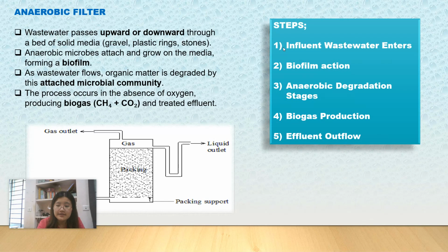The solid media inside the reactor provides a surface for the anaerobes to form a biofilm, for the microbes to attach. Now, after some time, these microbes form a biofilm, creating stable communities. That happens in the biofilm action. In the third step, anaerobic degradation stages, as I have explained in the previous slide, which is hydrolysis.